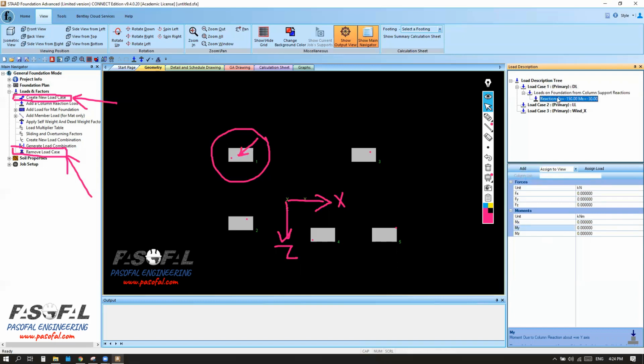And then add. See, right now I have this option here. Again, from here, I can say the second column, which means here. For sure I have the vertical load, so here I can change it to 130, let's say. And then moment, maybe I can change it to minus 10. And then also I want to apply moment around the Z local axis, so here let's say plus, I don't know, 15. It is for the second. Yes, okay, and then add. See here, I have also this one.